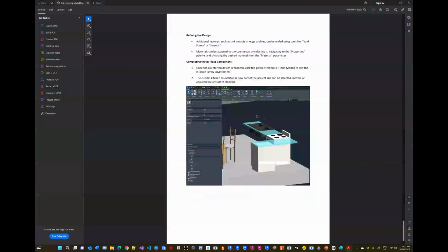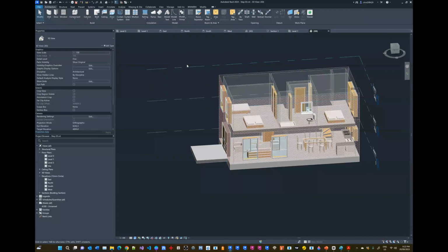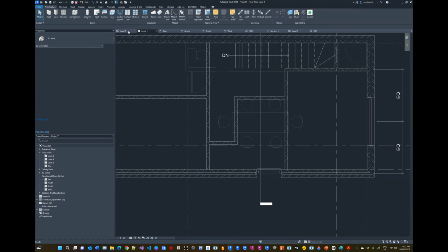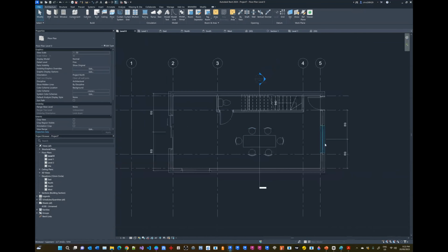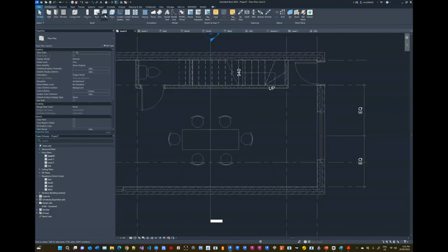There's one more thing that I could mention, and that's how to model that countertop in the kitchen, because that can be tricky. There are different opinions on how that is done. Some people use the floor component to model them. That is actually wrong, and that creates erroneous data downstream. So I'm going to show you how to do that very quickly, correctly.